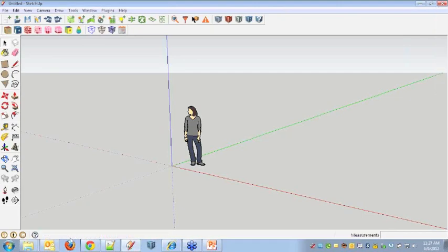At the bottom, you can see a progress as it's loading that in. And now I'm just basically going to draw the footprint of my building. So I'm going to use the rectangle tools to define that. And I'm going to click next to Susan, our scale figure here. And I'm going to click a point to start my rectangle, move over to the right.